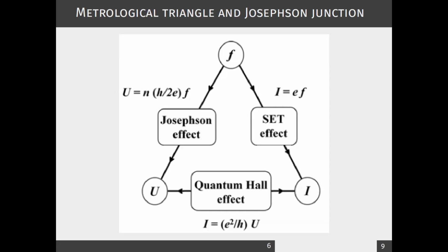Nevertheless, those three phenomena are interconnected. I should mention to you that if you apply voltage to a Josephson junction, and this voltage is of magnitude smaller than the size of the superconducting gap, there will be induced oscillations. So you will have a voltage controlled current oscillator, the Josephson junction. And then you can generate high frequencies of oscillations up to a couple of gigahertz, sometimes even into the terahertz regime. And this is in regard to high temperature superconductors. Josephson junctions, especially in D-wave superconductors, can be the source of terahertz radiation. Nevertheless, there is a problem with the high power of this radiation.